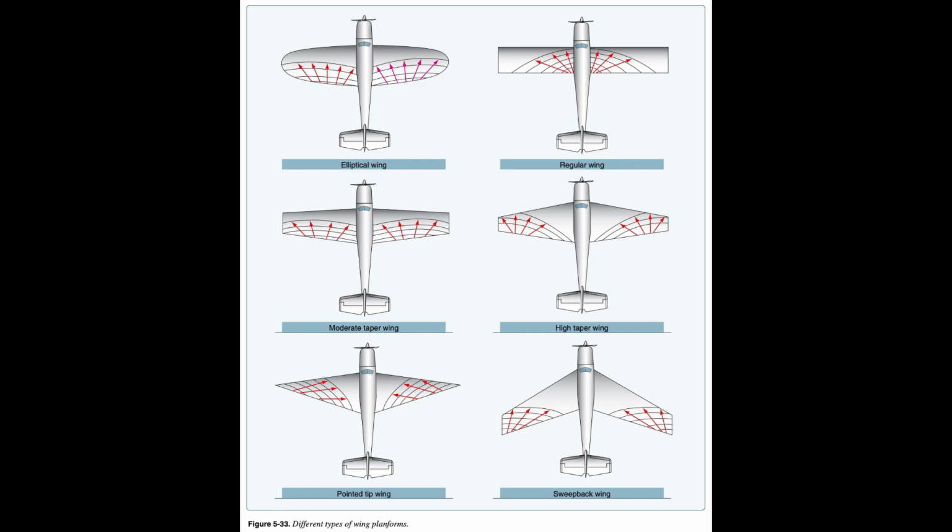The elliptical wing is the ideal subsonic planform since it provides for a minimum of induced drag for a given aspect ratio, though as we shall see, its stall characteristics in some respects are inferior to the rectangular wing. It is also comparatively difficult to construct.